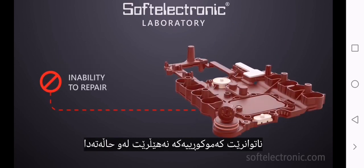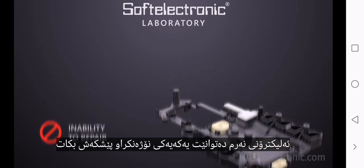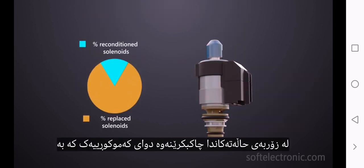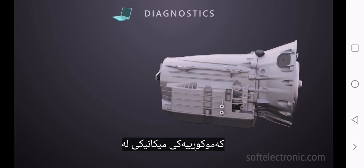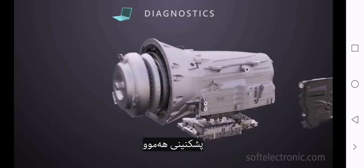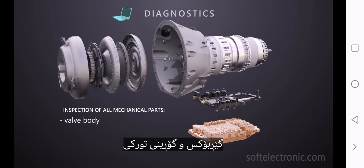Sometimes the defect cannot be eliminated. In that case, Soft Electronic can offer a reconditioned unit, which will be prepared for the relevant vehicle. Only a small percentage of the different solenoid models can be repaired. In most cases, after a defect, they're replaced with new ones. If a mechanical defect in the automatic transmission is determined during the overall diagnostics, the mechatronic is then scheduled for dismantling and inspection of all mechanical components, which includes the valve body, gearbox, and torque converter.